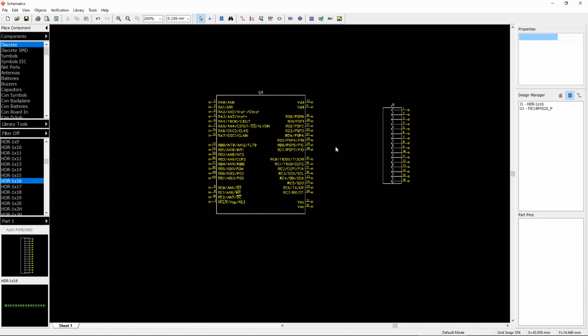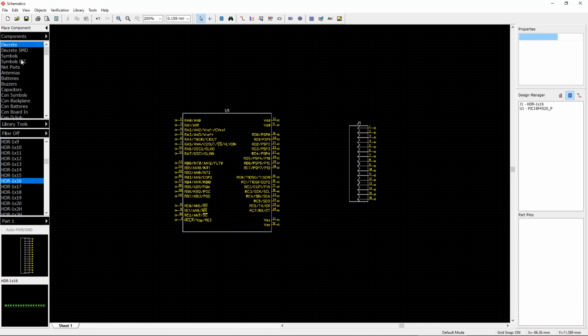When you pick these components on the schematic, you must make sure that they have the same dimensions as the physical component. If you just pick for no reason, because you like the appearance of the pins, for example if I click on this, you see this appearance as well. Let me look for another one like these ones. Okay, there are these other ones as well.